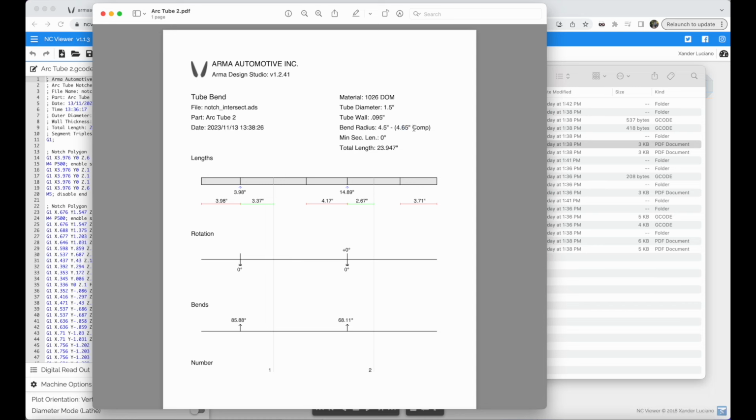When bending tube, the material will naturally spring back. So if you bend to 90 degrees, the material will spring back. So you won't get 90 degrees from a single 90 degree bend. It will spring back to 85 or something. The same also applies to the bend radius. When bending a tube, the bend radius when the tube is fully tightened in the die is 45, but as soon as you release the material, the bend angle is going to spring back, and the bend radius will also expand. So our CNC Tube Bender will compensate for the bend angle.